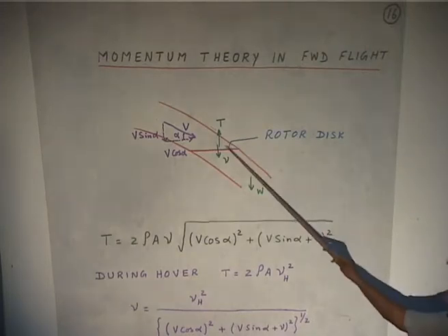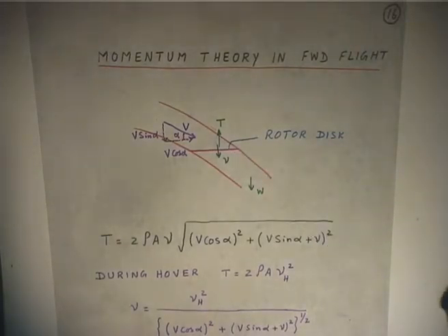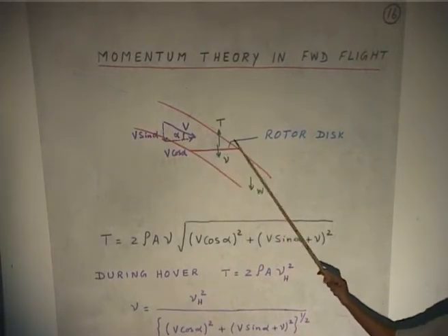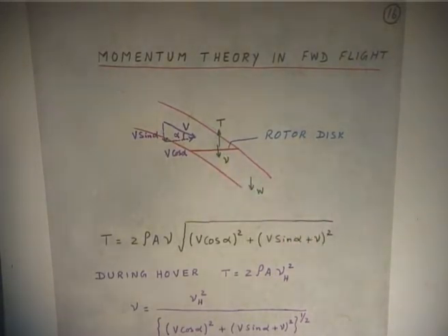And then I have put thrust, because the helicopter is in steady velocity, there is no acceleration, it is moving steadily. Thrust is up because it has to support the weight of the helicopter. So, for supporting that, there should be an inflow, okay. But that inflow is actually normal to the rotor disc, because I am pushing the air down, so I am going up.